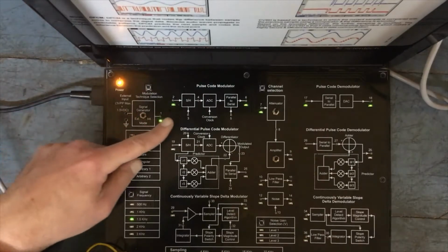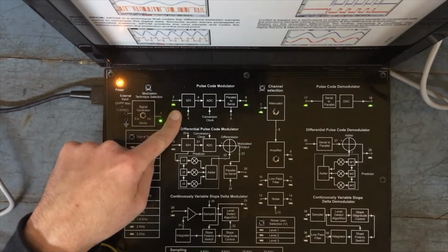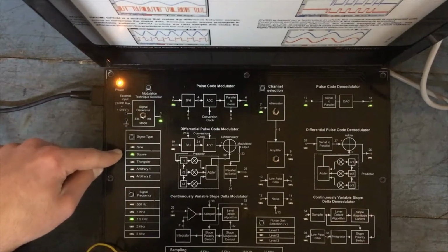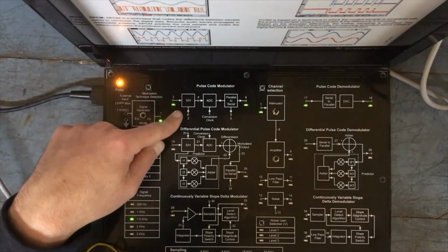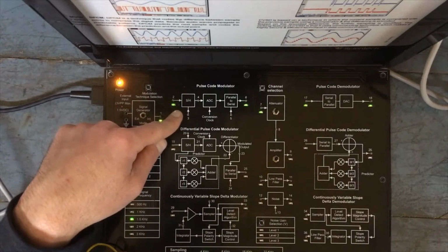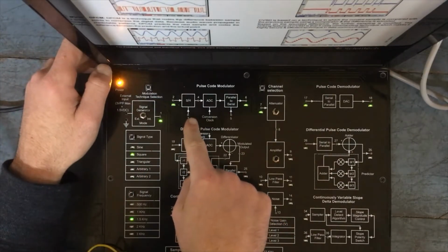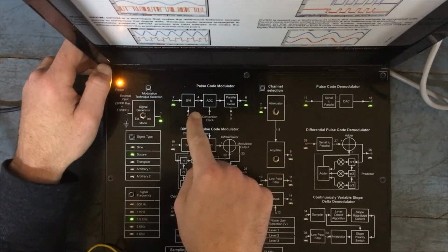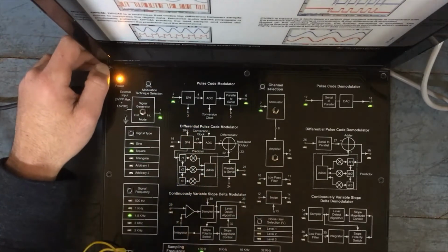In the pulse code modulator, the first stage, as you can see, is the sample and hold. So we give the input signal, let's say it is a square wave with some 1.5 kilohertz frequency, to the sample and hold block. The sample and hold block essentially is given the sampling frequency or clock from this input, wherein it takes the samples at the defined frequency. How to change this frequency is over here at the bottom.